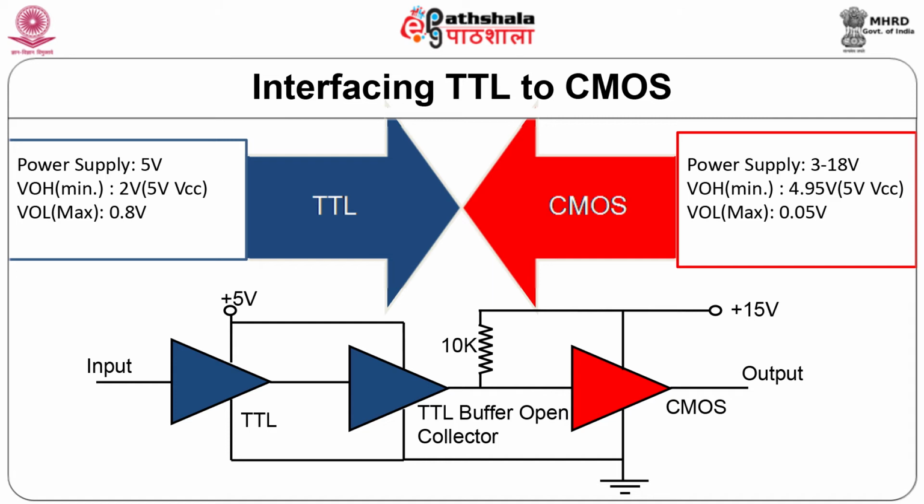When the two are operating on different power supplies, one of the simplest interface techniques is to use a transistor as a switch in between the two. Another technique is to use an open collector type TTL buffer.